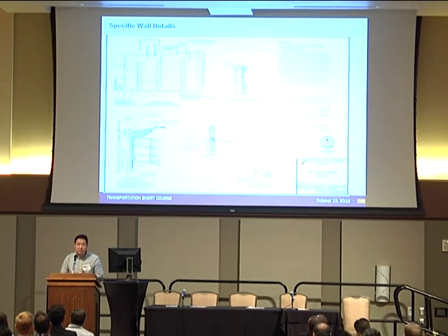If you just put in a soil nail without any shotcrete element, you are just poking a chopstick in the soil. It is not a system. The soil nail retaining wall only works as a system.